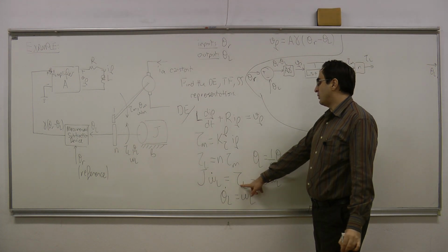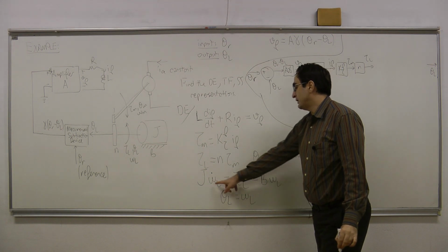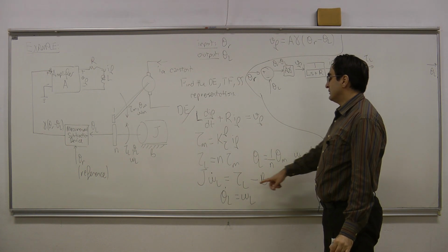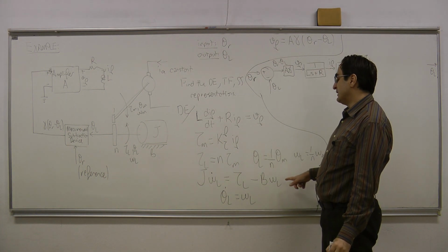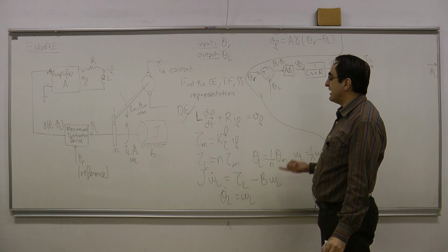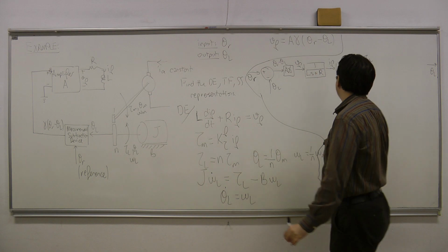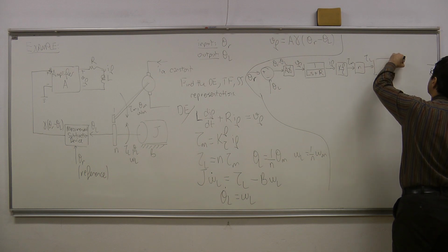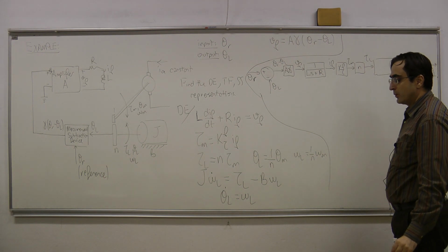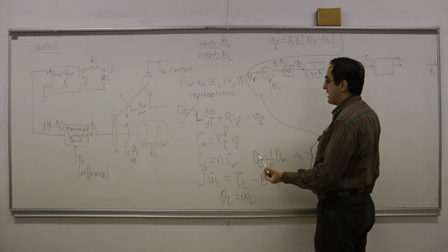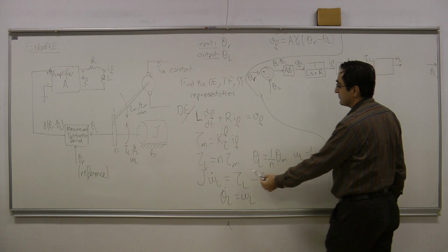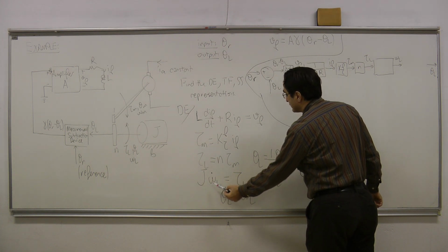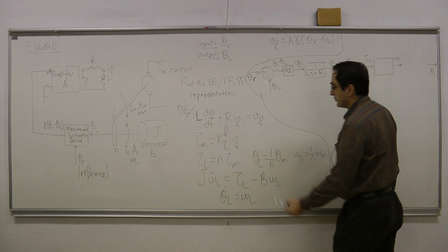And from tau L, I can go into omega L. So this equation is only related to omega L and tau L. Here, I can pass this equation into Laplace domain, and I can try to extract what omega L is in terms of tau L. So I will put here another system block, and that is going to give me omega L. So I want you now to pass this equation into Laplace domain in your mind. And while trying to do that, just try to express omega L, capital omega L, in terms of tau L.